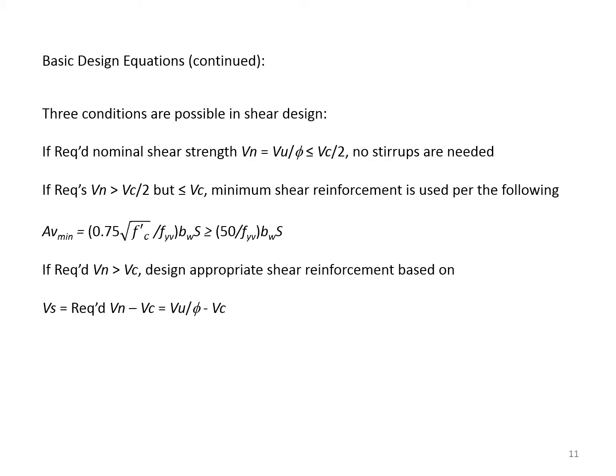3. If required V sub n is larger than V sub c, we need to design appropriate shear reinforcement based on the difference between V sub n and V sub c. In other words, V sub u divided by phi minus V sub c.